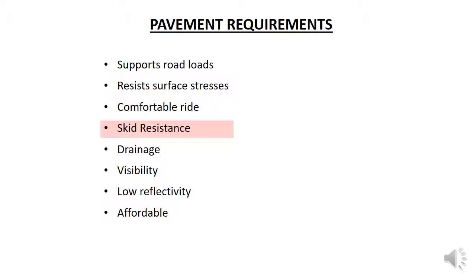The road surface needs to be able to provide skid resistance by having good traction between the vehicles and the road. It is this traction that allows vehicles to stay on the road even when turning, braking and accelerating. Over time, the road surface can be polished by traffic movements, resulting in a loss of traction, so surfacing in contact with the vehicles needs to be selected to resist being eroded by repetitive loading and weathering.